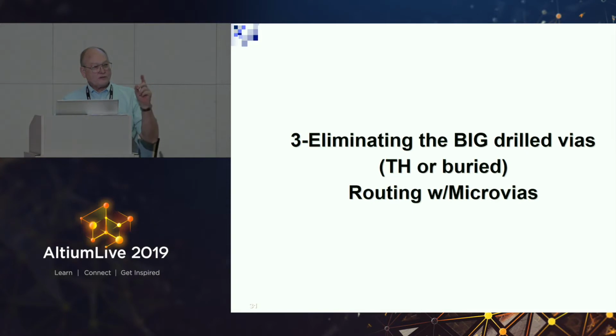The whole concept of if you're going to use HDI, once you use one laser drilled microvia, you're paying for the whole kit and caboodle. So the worst thing you can do is have a design that has 270 laser drilled holes, because you could have put in 20,000 laser drilled holes for the same price, because the laser drills about 600 vias a second. So the difference between 200 and 20,000 is the number of seconds.